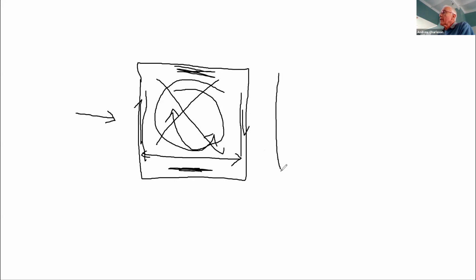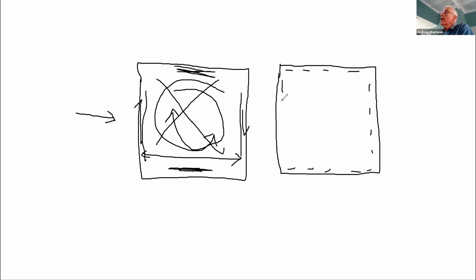So in this building, to stop torsion, one way would be to have a moment frame. These are columns. It's like 2 moment frames in the X direction, plus 2 moment frames in the Y direction. That will be more than enough to stop the torsion.